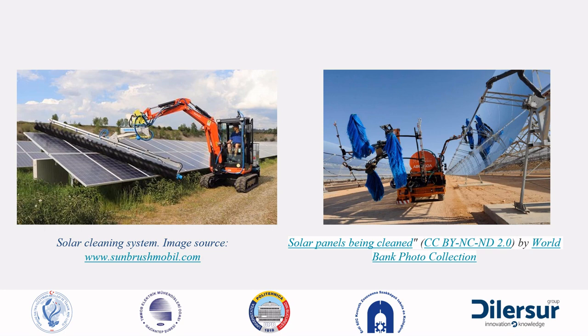The best is to clean solar panels when they are moist or wet, so any dirt or residue that is stuck on them can be wiped off easily. The best is to clean solar panels in the morning or evening. During the middle part of the day the panels can get very hot, making cleaning dangerous for both worker and the panels. It is important not to use harsh materials when cleaning solar panels, as they could cause damage.